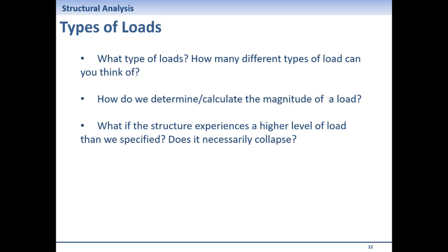Because there's another fundamental question there. We know that there is dead load. Dead load is the weight of the structure, and anything that is not moving, we categorize that as dead load, like the chairs that we have installed here, the carpet, everything that you see, all the architectural decorating elements that you see, plus the weight of the structure. So that's a dead load. As I said, we call it dead because it doesn't move. Then we have live load.